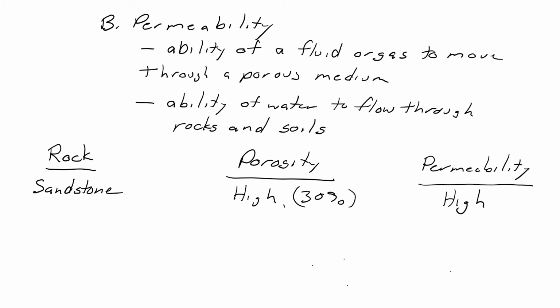So in terms of prospecting for groundwater, if you can find a sandstone that's saturated, that tends to be a very good aquifer because water can move and travel, and when you pump water out of the well, more water can come back in and replenish it because that's what you want. You want to be able to extract water from the ground, and you want that water to replenish itself as fast as you take it out.